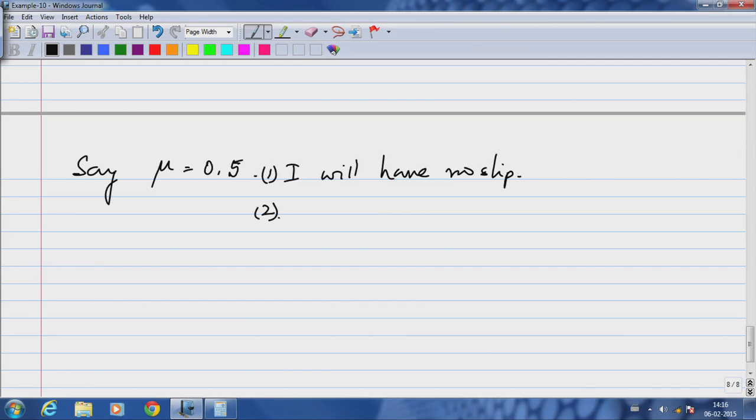The second observation: the maximum value of f, as we know from elementary Coulomb friction modeling, is mu times n. So, in this case the maximum value is 0.5 times 96, which is 48 newtons.